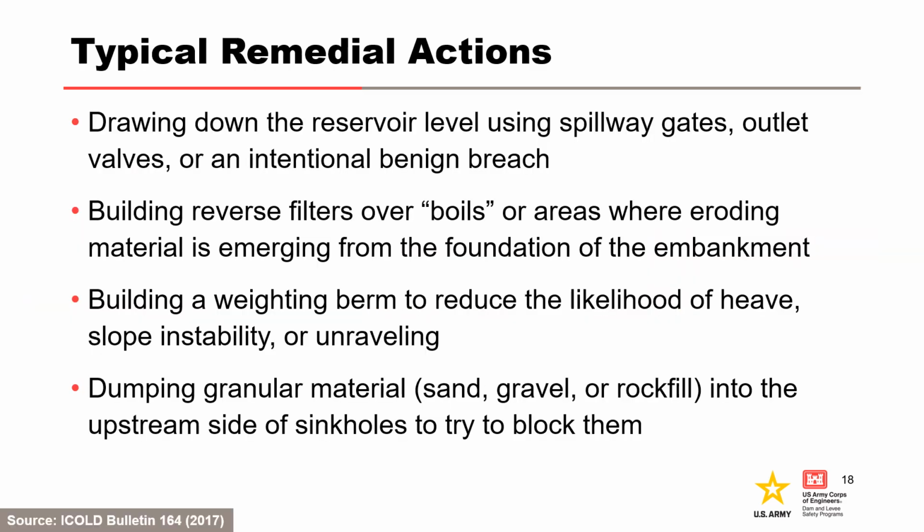Some typical remedial actions that we can take are shown on this slide. In addition to drawing the reservoir down, some structural actions include building reverse filters over boils or areas where eroding material is emerging from the foundation or the embankment, building a weighted berm to reduce the likelihood of heave, slope instability, or unraveling, and dumping granular material such as sand, gravel, or rockfill into the upstream side of sinkholes to try to block them. More than one of these measures may be used together.